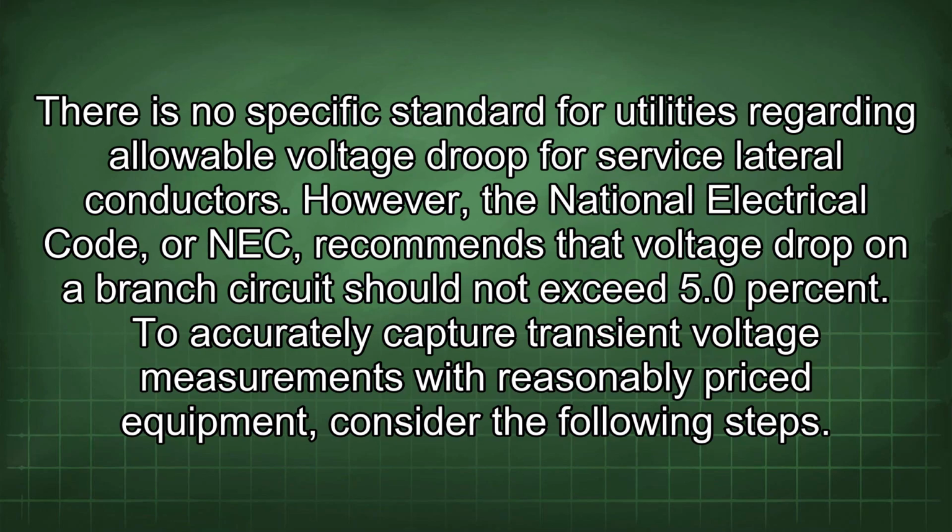There is no specific standard for utilities regarding allowable voltage droop for surface lateral conductors. However, the National Electrical Code, or NEC, recommends that voltage drop on a branch circuit should not exceed 5.0%. To accurately capture transient voltage measurements with reasonably priced equipment, consider the following steps.